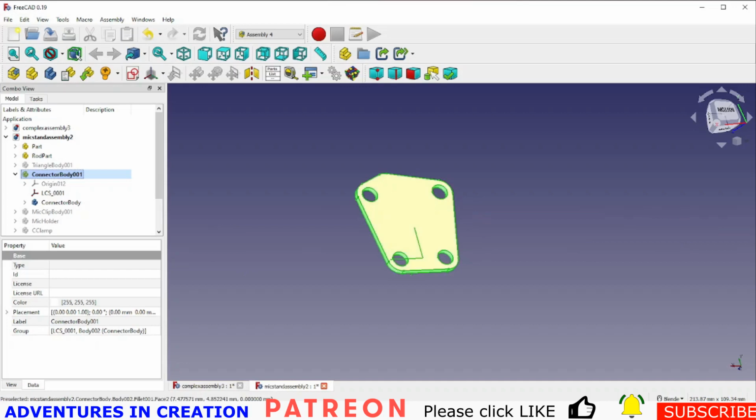So now I'm going to make 4 LCSs on here so I can assemble that. Now I'm not going to make you watch through all of this. I'm going to show you this one, and then when I'm done, I'm going to stop the video. I will go ahead and create all the LCSs in all the parts ready to go. But they're all going to be exactly the same. We're all going to be picking a circle and putting an LCS in every single circle, because that's how it's assembled in this case. So I'll show you how we do this one.